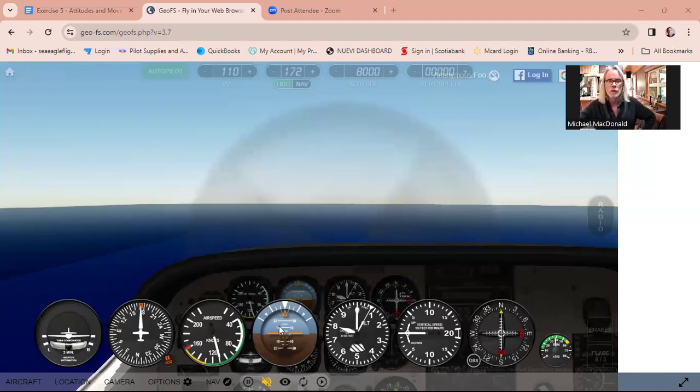Also, you'll see there's an orange and white arrow. When this orange arrow moves left or right, that's indicating a bank, and the horizon would be skewed. So basically, it's showing you what's out the window. You don't really need it if you're looking out the window in visual reference flight, but you can cross-check it.